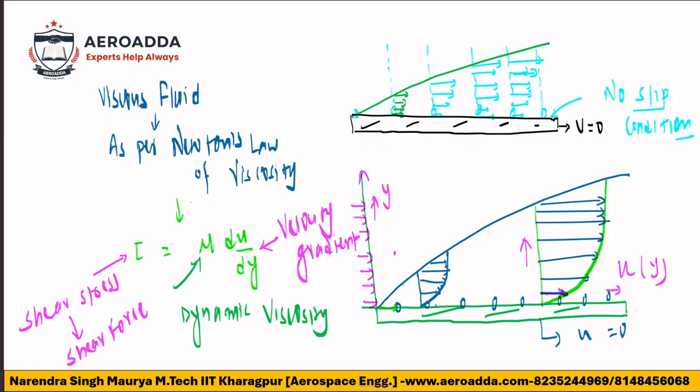So now the flow will not be a uniform flow, not a straight stream flow, because of this viscosity effect. Near the surface of the plate there will be a disturbance, and it is a very thin region actually. But it will try to oppose. Exactly at the surface of the plate the velocity is zero. But as you move away, it is increasing.